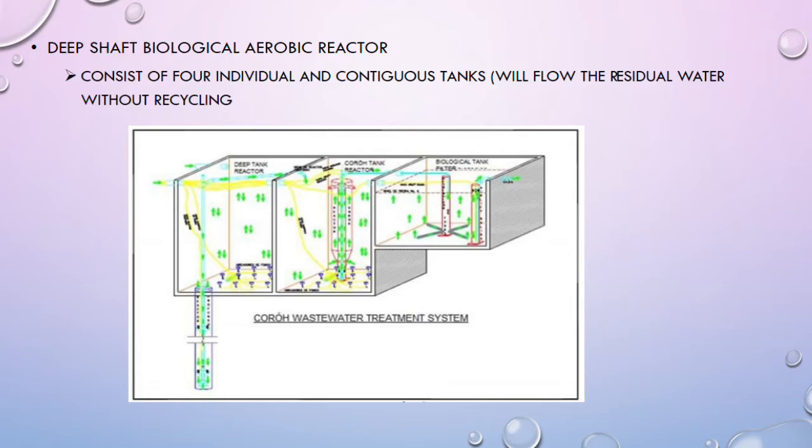Based on the experiment done by Jackson and Shen in 1978, they said the homogenization tank makes a homogeneous mixture of the effluent and it is conducive to the deep shaft reactor tank, which offers minor energy consumption in the discharge oxygenation capacity, low cost and low maintenance, elevating the partial pressure and the oxygen solubility, distributing the fluid to the sedimentation tank and through a secondary filtration percolation treatment.